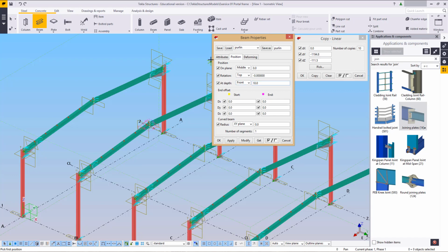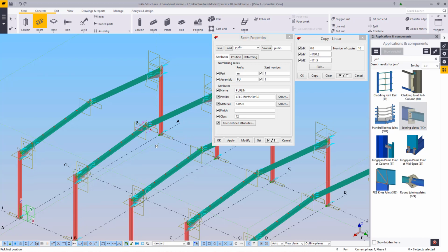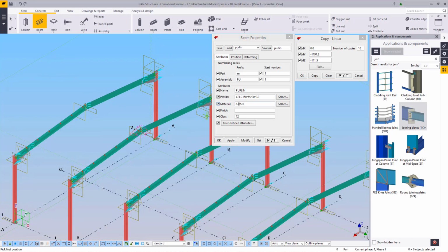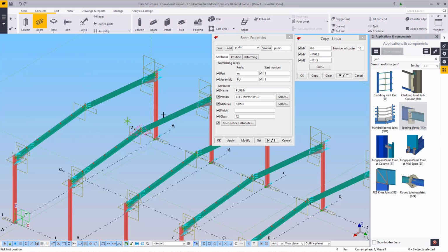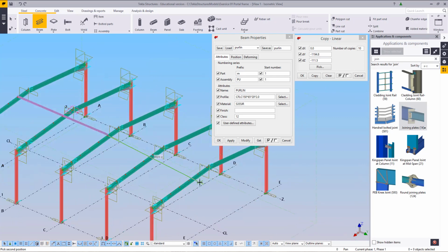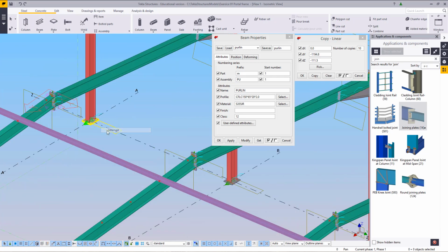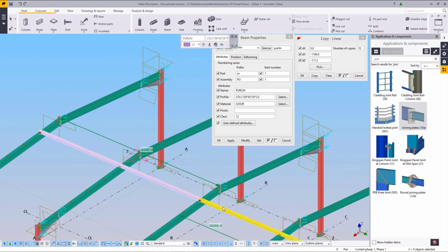As you can see, front 10, all the other settings, and I will explain them as we go along. Firstly, make sure that your material grade is S355JR as our standard material grade, or whatever standard material grade you need to use. Like a lot of these things, they tend to have presets that define what they think it should be, and that is not necessarily what you need. So, just going to select both of these.